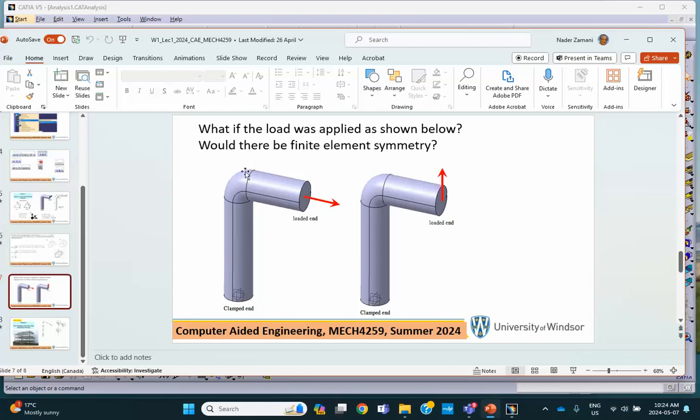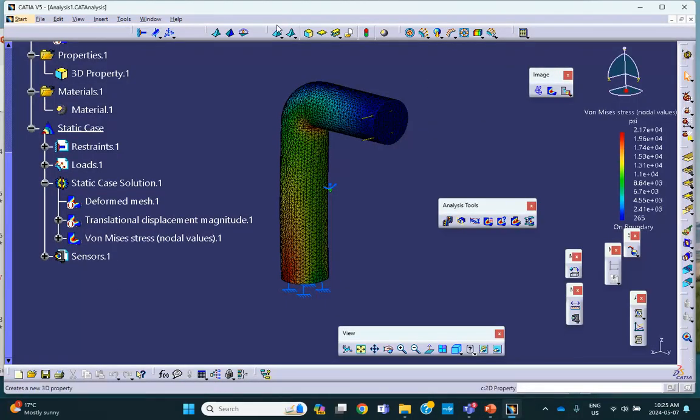When you cut it so that you get half of it, that face that is introduced, you have to put a surface slider or a roller on it. And what do I mean by a roller? Where is that? There, this is a clamp, this is a surface slider, and there are other options here too, but this is a surface slider, which is called a roller in some of the packages.